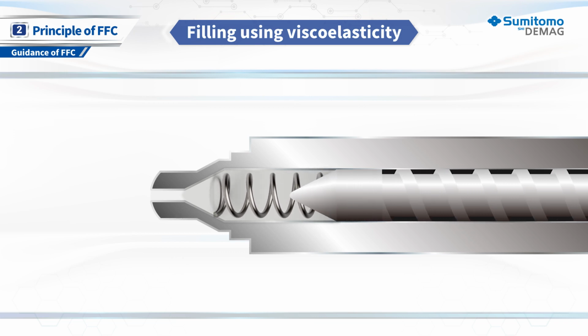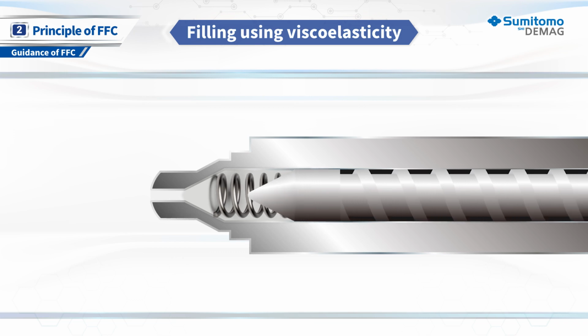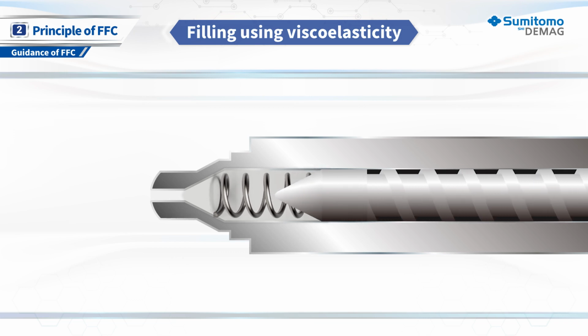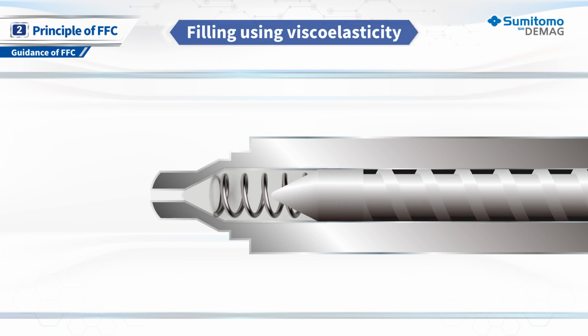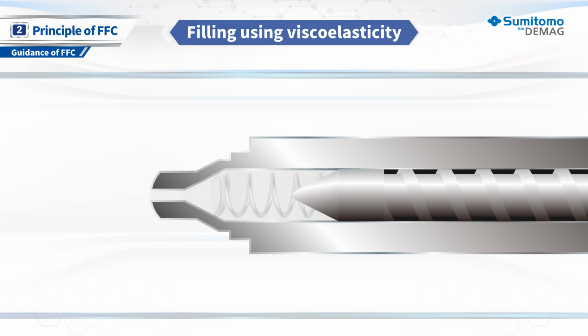The viscoelastic property also appears in the forward and backward motion of the screw in the cylinder during molding. Now, let's imagine the relationship between the pressure and the resin volume when the tip of the nozzle is closed with a stopper and the screw is advanced.